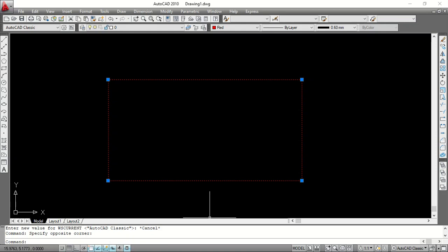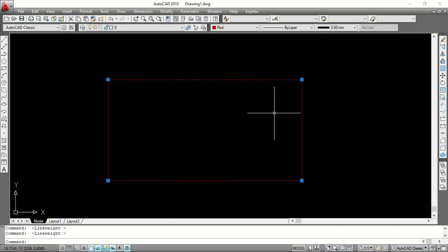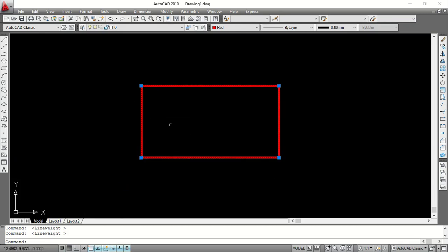Now, when you come down here, you're going to see some other tools that will help you to do your drawing successfully, to get a perfect job done. Then you come here, you see show stroke height line width, and you click that. It shows the actual line width, but if you switch this off, you won't see anything. So it's important when you're doing your design, keep this on so you see the effectiveness of your layers, especially the line weight, on your drawings. That takes us quickly to this bar. Let's start looking at them one after the other.